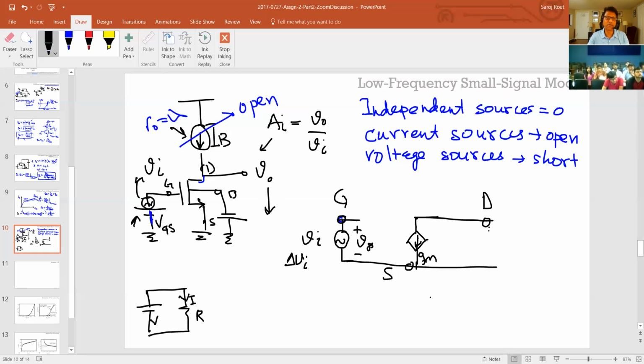So if your incremental voltage is changing in a certain direction or a certain phase, and it is exactly the same phase in the incremental change in current, you keep the direction the same. So when you start writing the current times resistor and all that, everything becomes coherent. Otherwise, you'll get your phases wrong, right? So you have to be careful with that.